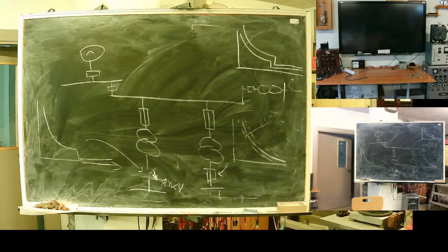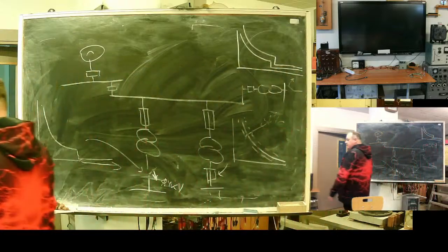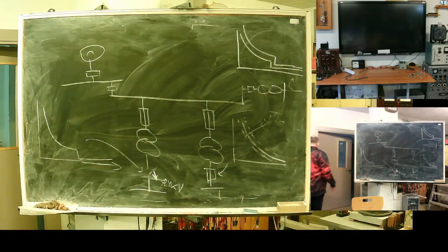And this oil, in summertime, relays operate smoothly. In wintertime, oil freezes, not like ice, but it's more viscous. And the relay fails. Useless thing. Use digital. Don't waste your time, put in a digital one. Digital will work fine. But what kind of characteristics should they have?